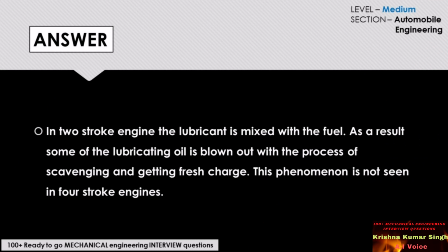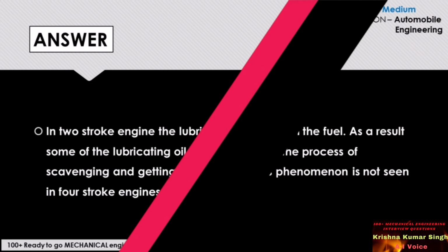The perfect answer for this question would be: in two-stroke engine, the lubricant is mixed with the fuel. As a result, some of the lubricating oil is blown out with the process of scavenging and getting fresh charge. This phenomenon is not seen in four-stroke engine.